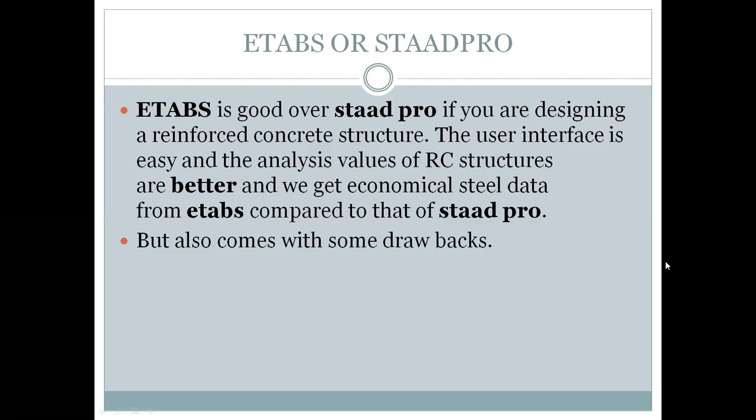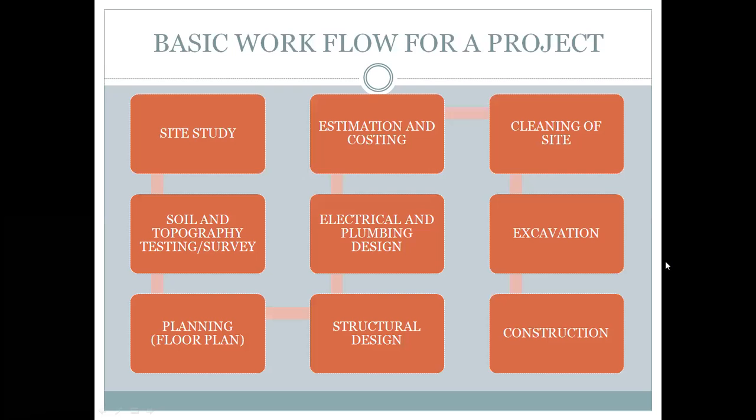Next, a lot of people are confused, ETABS or STAAD.Pro. Both of them are good. The only thing is STAAD.Pro is a very vast software which includes every type of structure, whereas ETABS is only based on buildings. And secondly, ETABS gives us lower values for steel, so it gives us the economical part of a building, whereas STAAD.Pro on the other side relates with more safe, hence less economical type of structures. And when it comes to user interface, ETABS is more user friendly than STAAD.Pro is.